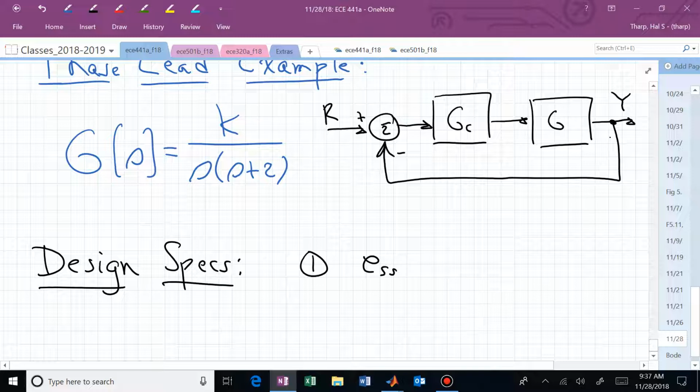But your system will get faster in terms of how quickly it gets to the peak, but it'll still take the same amount of time to settle. So your settling time is the same. It gets there quick, but it gets far away from where you wanted, maybe, if K is big. But you see all of this now, right? Just by looking at G.